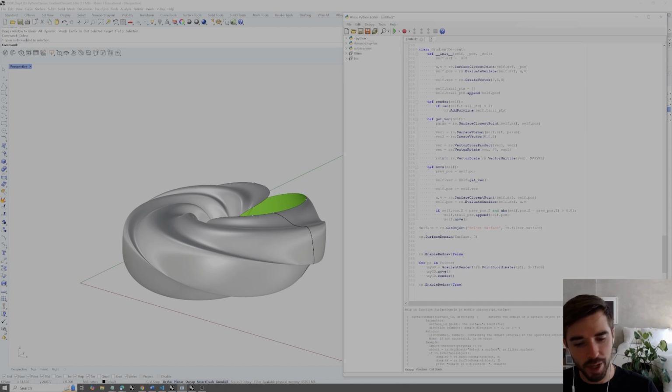So we can unpack this as umin, comma, umax, and set that equal to the output of surface domain with an input of both surface and 0 to get those u values. Now if we copy and paste this down, to get the v's, we just need an input of 1, as it says here in our help function. And now we need to say vmin and vmax.